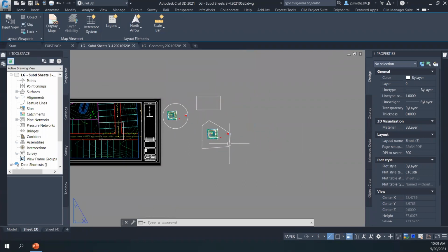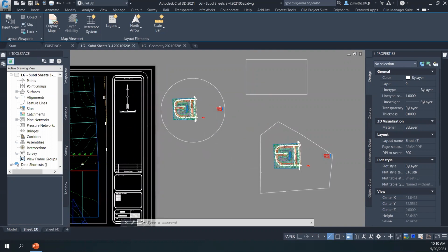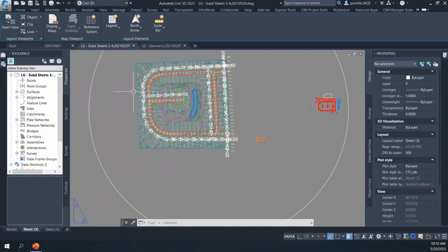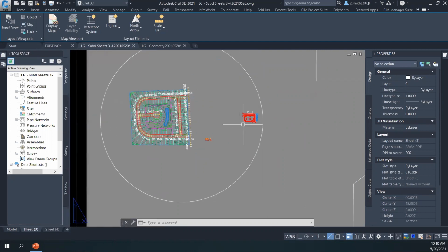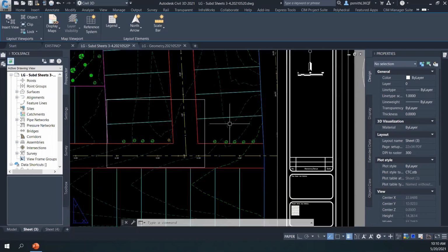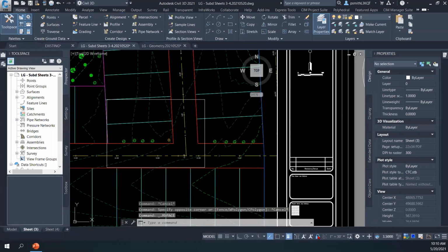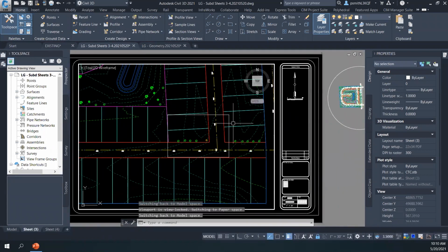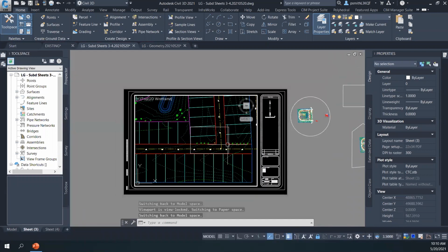So the next one is something that I have found not very many people know. A lot of people know this command called dview twist, and that's how they rotate their viewports around. I feel like that's kind of an older method of sorts. And let's say on this viewport, I unlock it. Oh, another thing is always lock your viewports. Big tip there. Many people know about it. Not too many people actually use it. So you hit that lock button right here. Whenever you're done messing around with the viewport, setting your scale, big tip, hit the lock button. Saves a lot of headache.